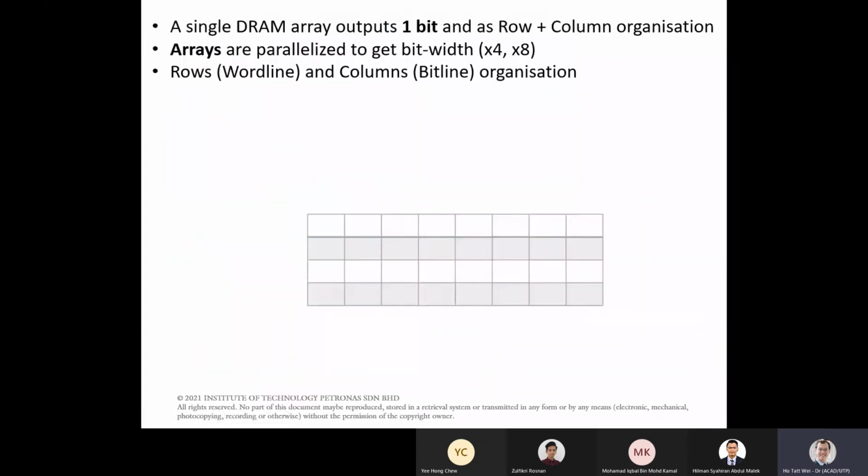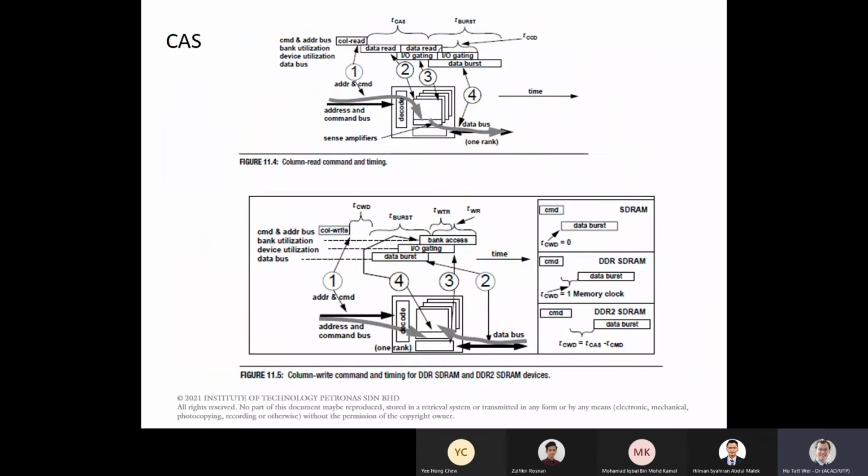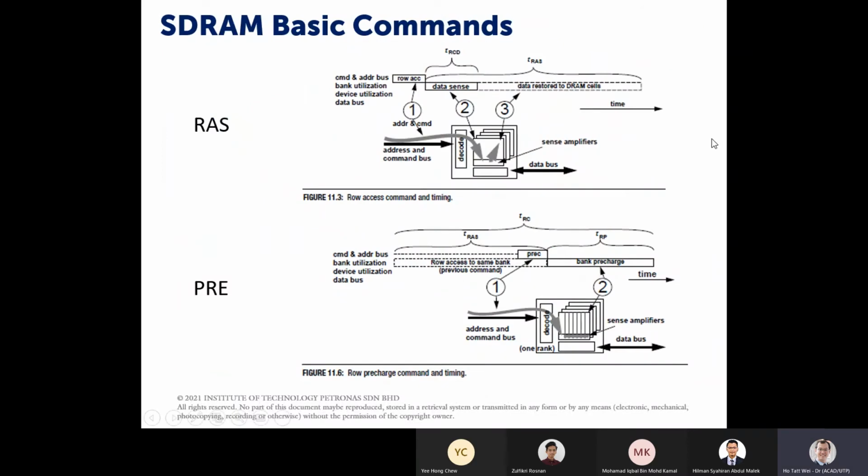Okay, so the pre-charge command is basically, you have to put some kind of pre-charge command here, but it is usually about the same time as the row access strobe. And then there's a certain amount of time for the pre-charge to happen. And this is the total amount of time, TRC.